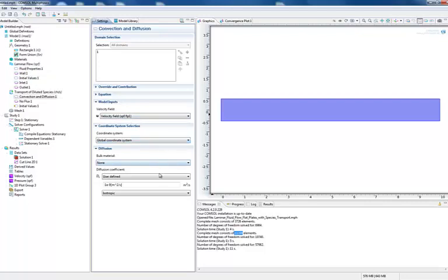Now in the diffusion coefficient user defined, let me just define it as 1e minus 2, just to be in conjunction with our geometry, because we have defined our geometry in meters. So that keeping our effective Peclet number low, I just define it to be 1e minus 2, and you can also select these different options. So isotropic means same diffusion coefficient is applied in both x and y directions. So we have defined this diffusivity for the species C transport.